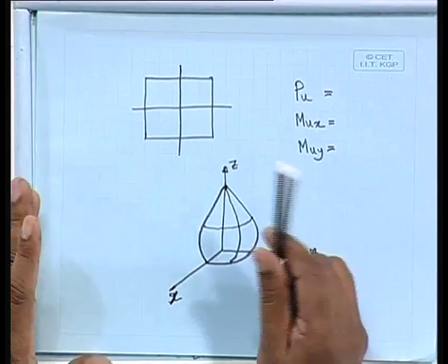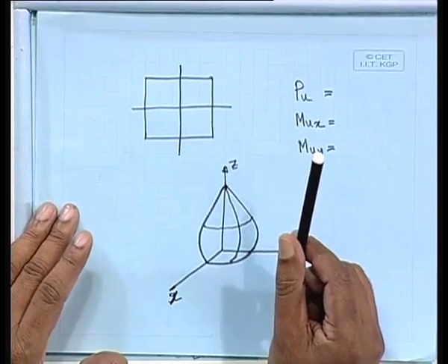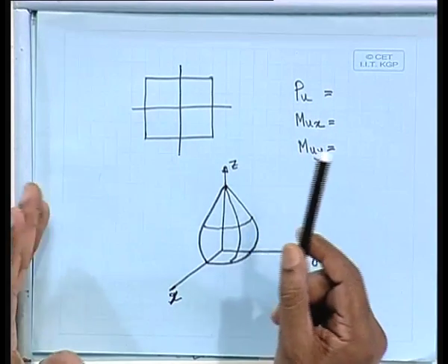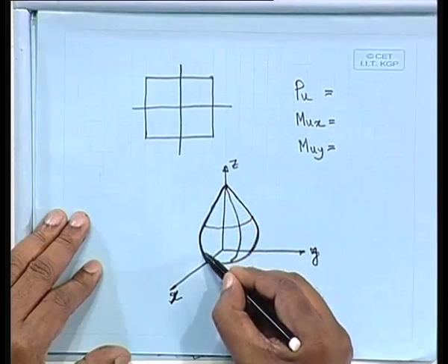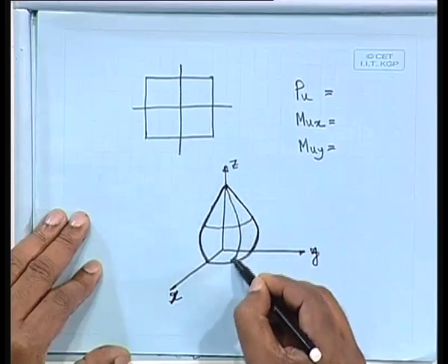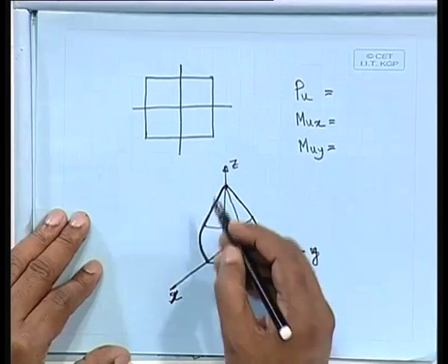that we have got, and that is given in SP16 also, and one can make it on your own also. That means you can develop it on your own. There is nothing great, you can develop your own thing also. Anyway, that we shall come to later on. What I am trying to say, the curve you are having along this axis, that means y and z axis. So, we are having this one interaction curve. Similarly, z and x axis here, that is also another curve. That means in another axis somewhere I can get another one. So, like that I can make so many interaction curves.